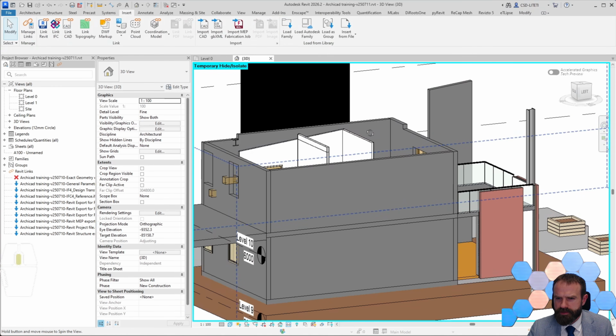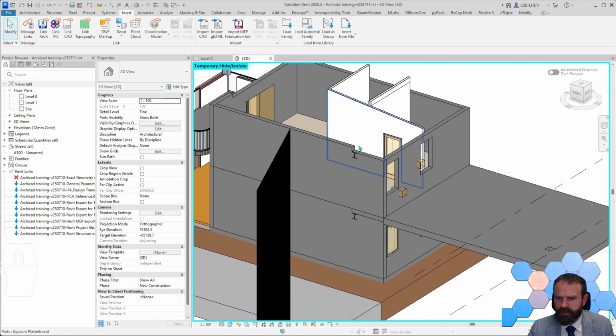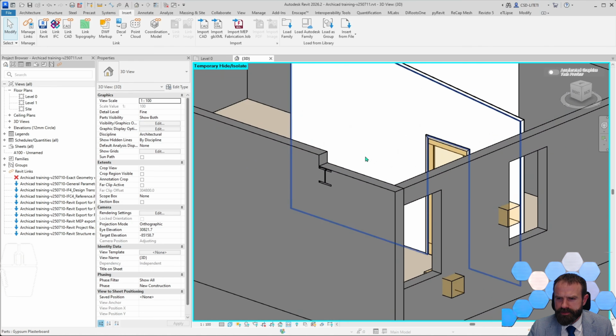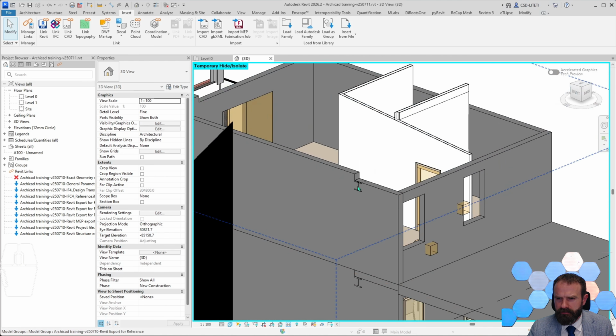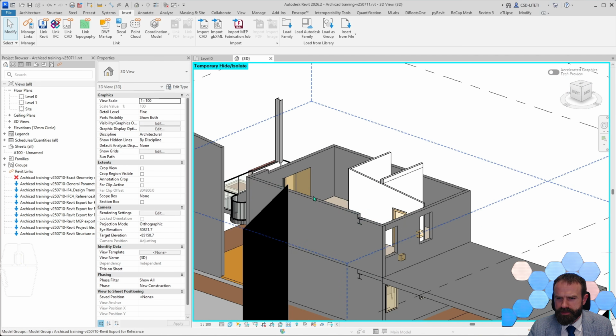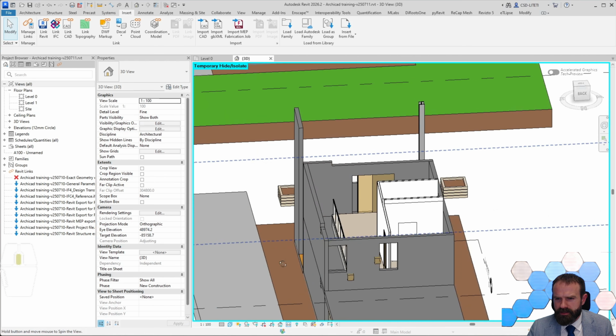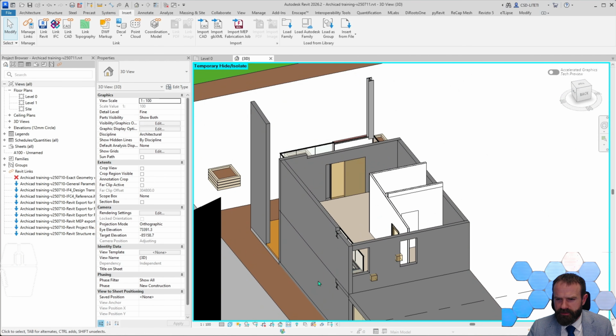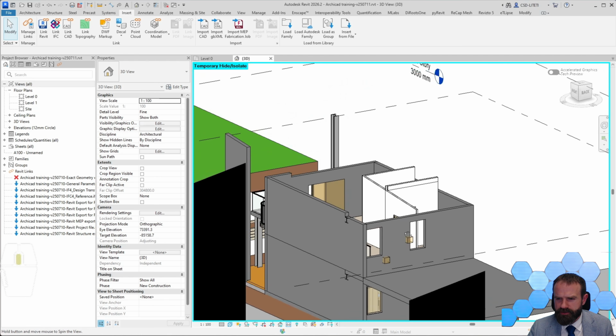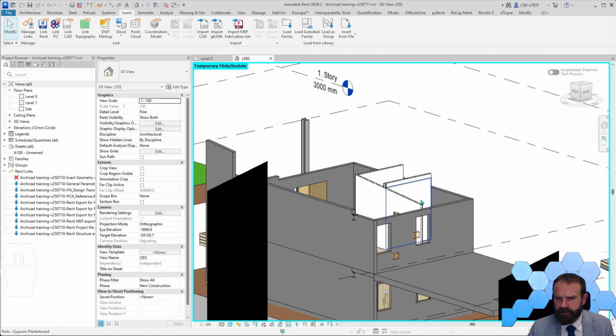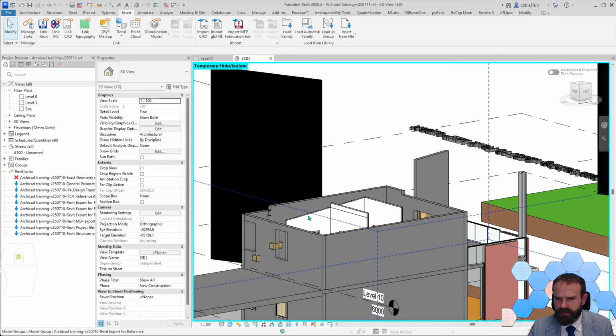And my wall's top orientation is created incorrectly, and also I see some openings, so it means it just copied the first floor and just moved it as a copy to the second floor.